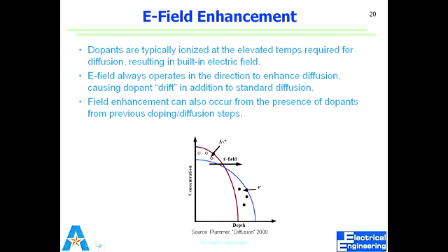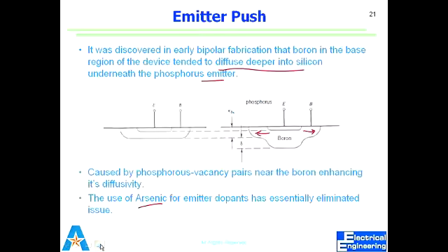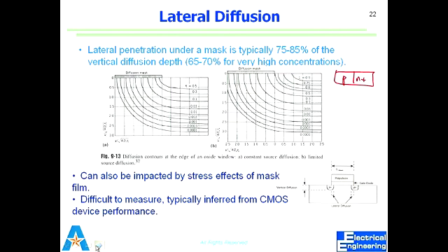So diffusion is not just what we want to do with silicon. We are worried about diffusion through other material. We want to do diffusion in polysilicon, in the material that comes after we make the device. And it restricts the temperature that we can use afterward.